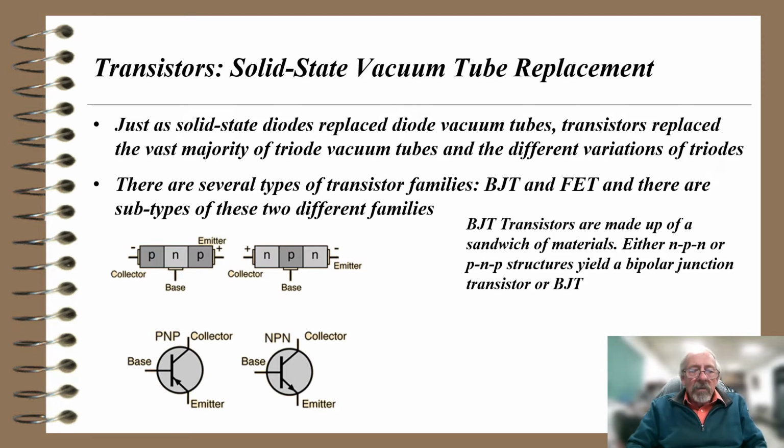So you take a look at the top portion of that little picture. There's a PNP device, and it says collector, base, and emitter. So that's a PNP transistor. The symbol for it is down below, and the element has 3 terminals, much like a vacuum tube: collector, emitter, and base. You control the transistor through the base lead, and you can turn the current off between collector to emitter. Now, by the way, the PNP is pointing in. The little arrow on the emitter lead points in. So that's a PNP, pointing in, we'll say.